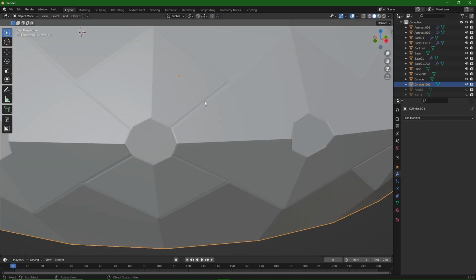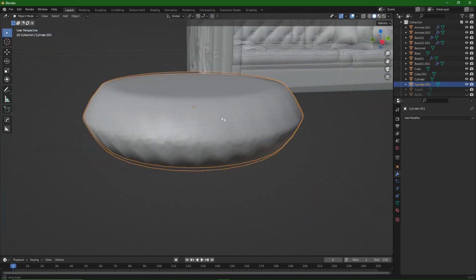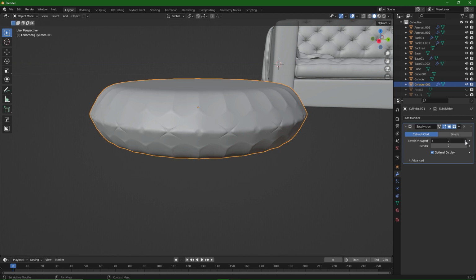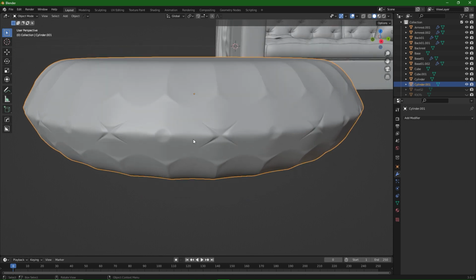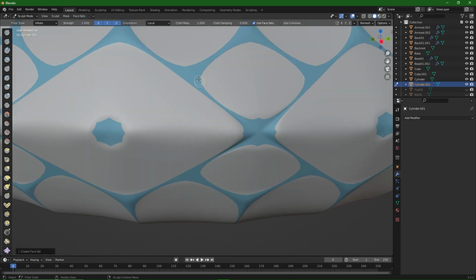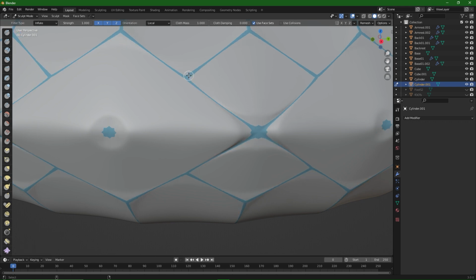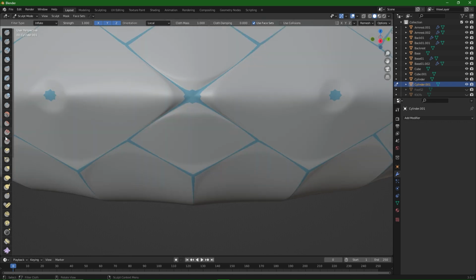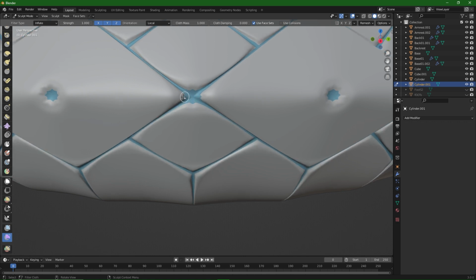And now we can go over to Shade Smooth, and then Subdivision Surface Modifier, and we just add 3 segments to this and apply. Alright, so let's see what happens once we go into our sculpt mode. And let's select our new facets, and let's just bring this down a bit, smallest form we can, right around there. And then make sure to use your cloth filter and on inflate over the highlighted part, and we just drag inwards.